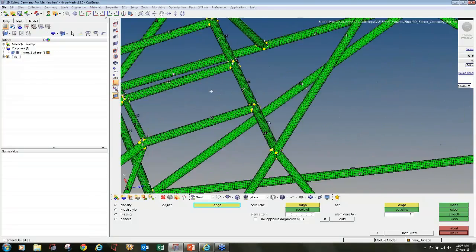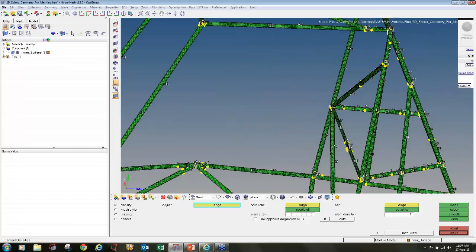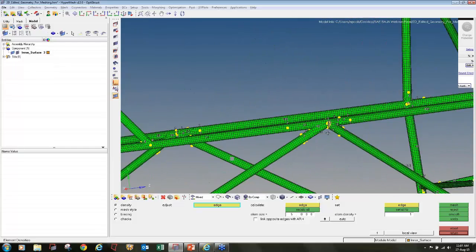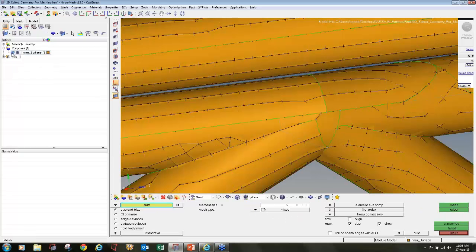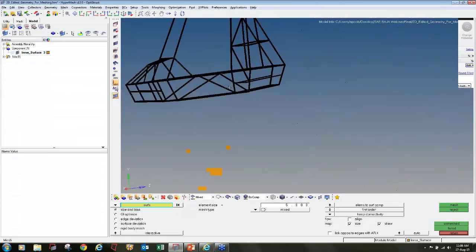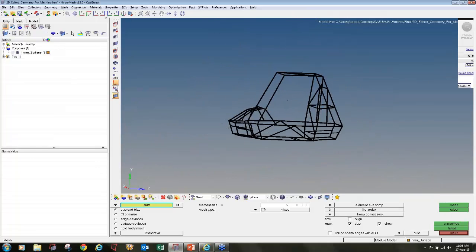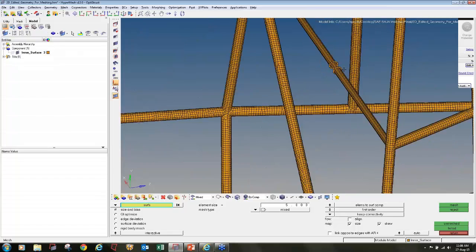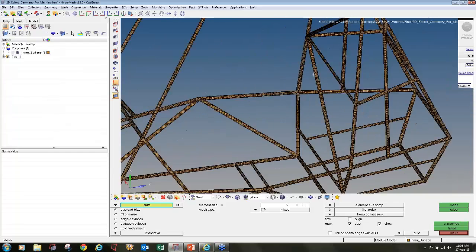So it has also said on which surface it is not able to create the meshing and which surface is failed. That I will check later on. So I will click return, turn off this. So I have the elements. This icon is for viewing the surfaces or edges, and this icon is for viewing the elements. So I'll turn off this, and I have a check to see all the elements are connected or not. If these elements are not connected, it's okay, but other than that all the elements have to be connected.